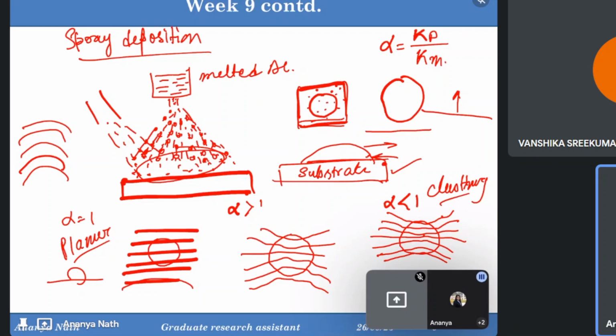So now the 1, 2, 3 series, these are the non-heat-treatable alloys. Not 2, but 1, 3, 5. I think these are the non-heat-treatable alloys. The 1 series is also not heat treatable, because it does not have any solute atoms. So we cannot play with the modulus interaction or electrical interaction, neither the precipitations. So 1 is typically not heat treatable.